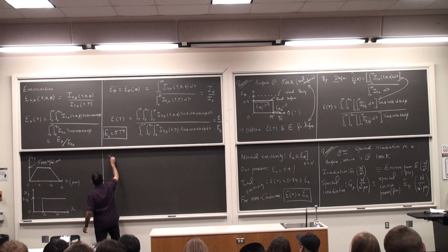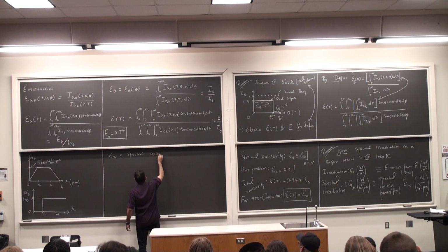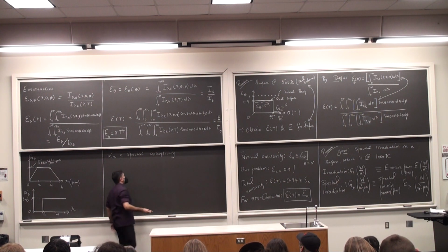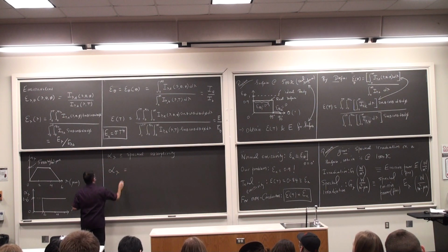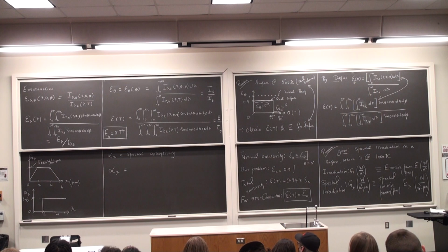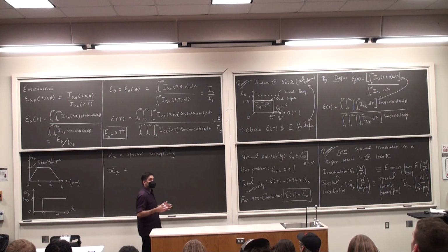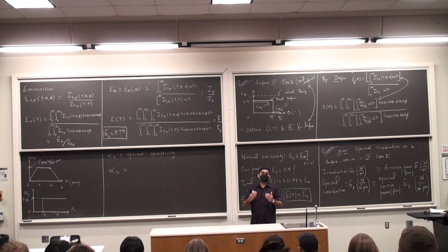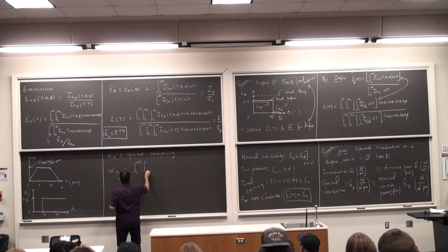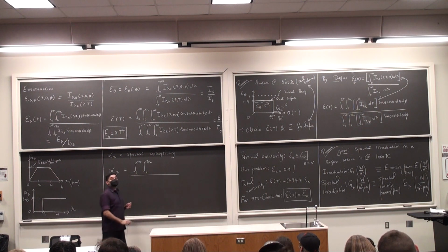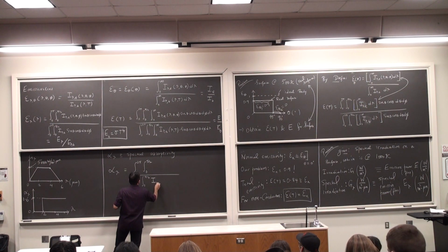So alpha lambda is the spectral absorptivity. It is defined as the following. Like we had I lambda comma E for emissivity and so on, we have the intensity of the incident radiation when we are talking about absorptivity and all these characteristics. And essentially we are comparing how much is absorbed versus how much is incident on me. Okay? So this is going to be integral from 0 to 2 pi, 0 to pi by 2. I'm first going to write the denominator, 0 to 2 pi, 0 to pi by 2, I lambda.